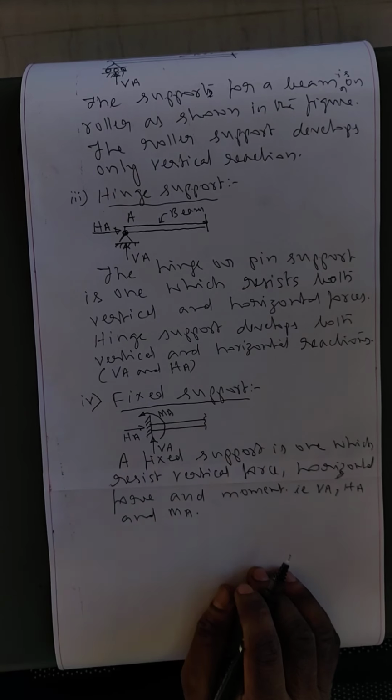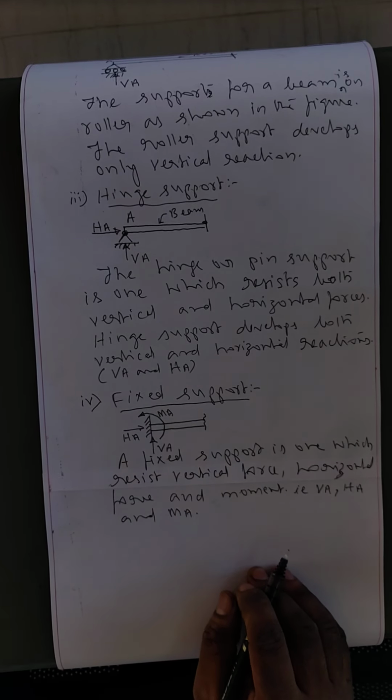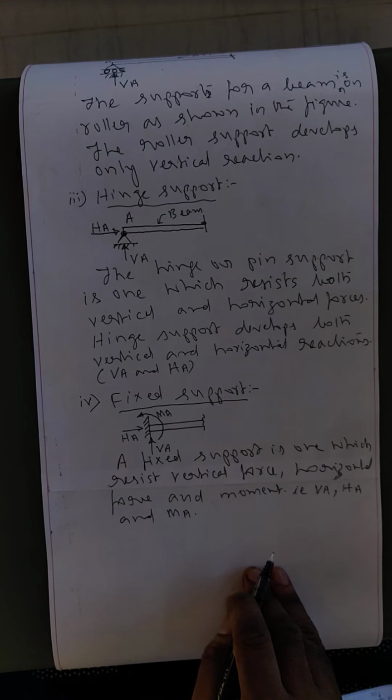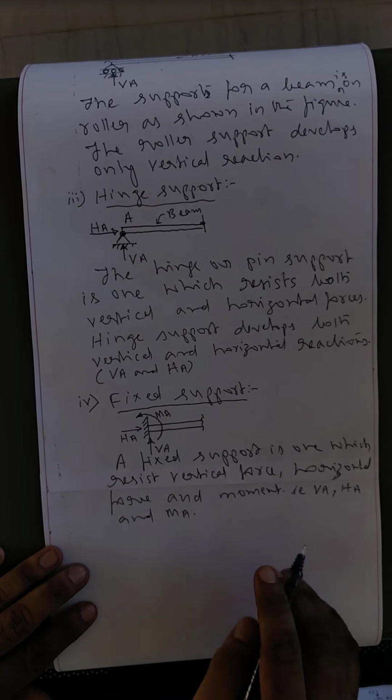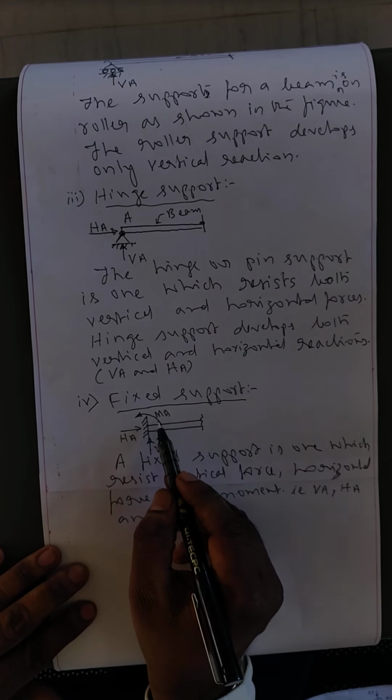A fixed support will develop the reactions in three directions: vertical, horizontal and rotational.